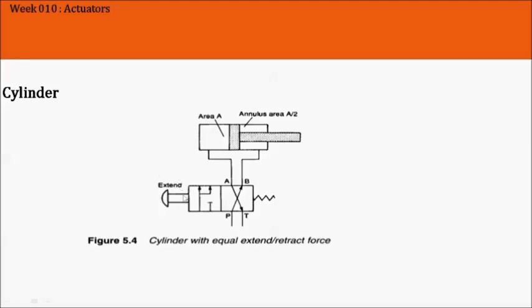Now you can adjust this motion. You can make it fast forward. It depends on the pressure of the pneumatics or the pressure of air. When you make it a large pressure of air, then this will move forward. It depends also on the type of cylinder you will use.